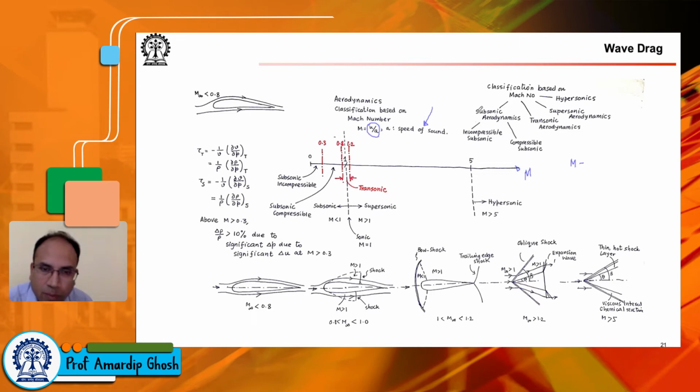Of course, right now perhaps this will not make too much sense, but keep in mind that Mach number, Reynolds number, and something known as Prandtl number are known as similarity parameters. So if your aircraft is flying at 30,000 feet, and you want to study the pressure distribution, the moment around the CG, how the boundary layer might behave, and you want to study it in the wind tunnel, you have to make sure that the similarity parameters for the problem in the wind tunnel are the same as those in free flight.